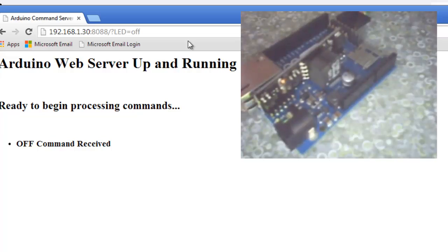So pretty straightforward. That's sending commands to the Arduino using the default connectivity model, which of course assumes that the device itself is addressable, and obviously in this case I'm using an IPv4 address, which really wouldn't be practical in a real scenario. Typically you'd have IPv6, maybe using VPN to bridge the connection, and it's really the device's responsibility to set up the server service API and expose that API for command receipt.